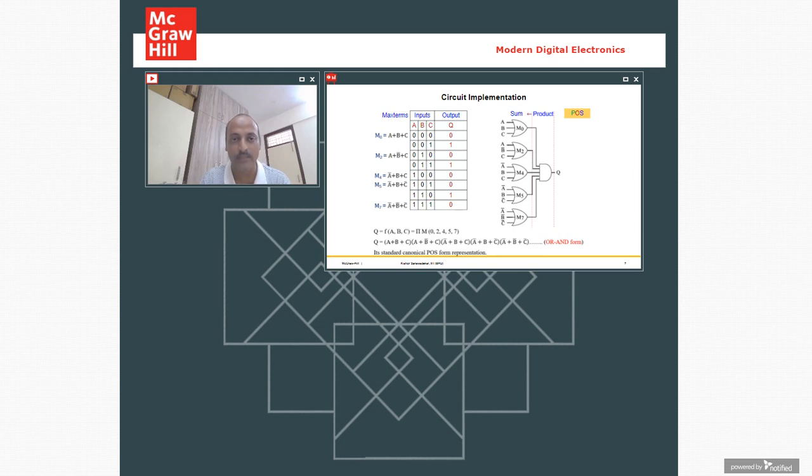But this plus is nothing but a logical operation, a Boolean operation. Okay, so it is ORing. So all these max terms will be summed. Finally, on the max terms, we will be operating AND. Okay, so what we call this is a product of sums. The first operation is summation, and finally we are doing product. Product is nothing but AND gate. So while calling this kind of Boolean expression or logical expression, we call it a product of sums.